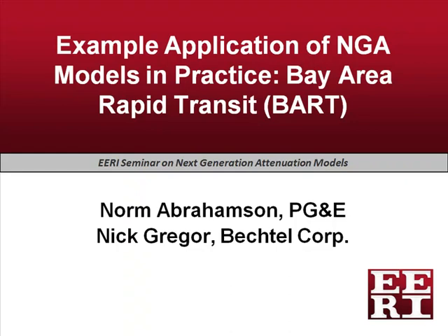And then, of course, since 2002, there was this new knowledge in specifically the NGA models that they felt they could take advantage of, that there were some better estimations of ground motion. There was a decrease for typical strike slip earthquakes in that region, and they felt that they could take advantage of that.